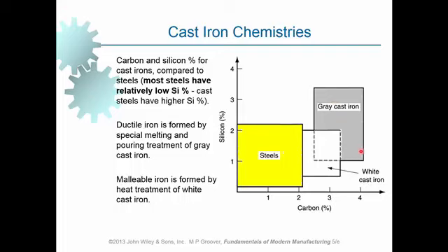We want cementite to be present in steels because it is very hard and it increases the wear resistance of the steel. But we don't necessarily want large amounts of cementite in cast irons. Rather, we are interested in having some deposits of carbon, graphite, in it. That is indeed carbon. When it is concentrated in certain regions, we call it graphite.